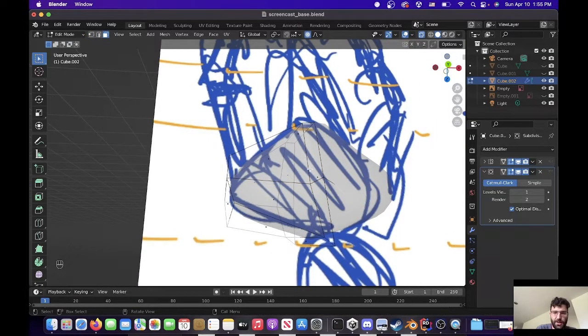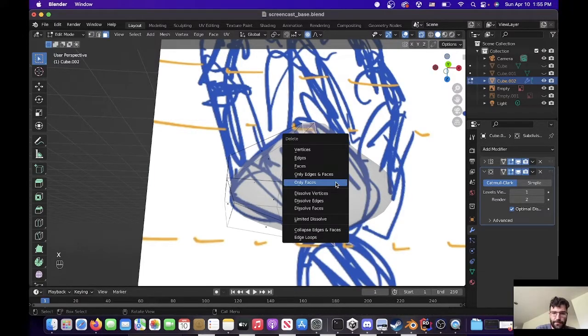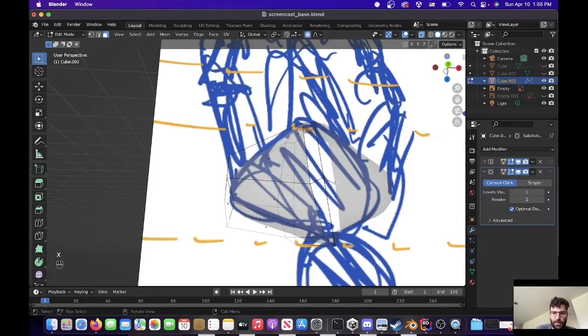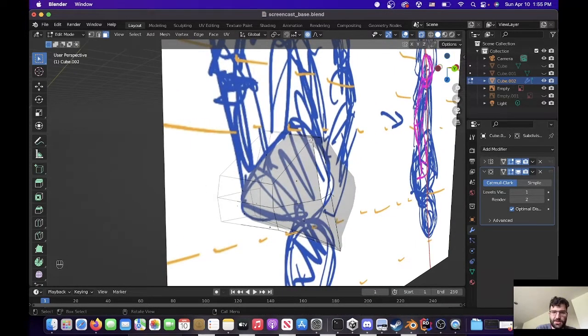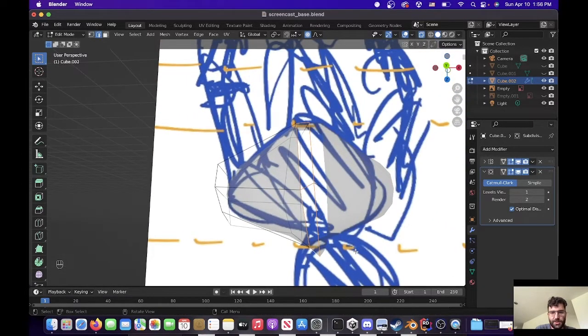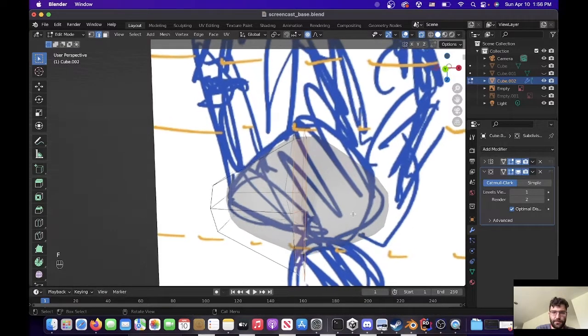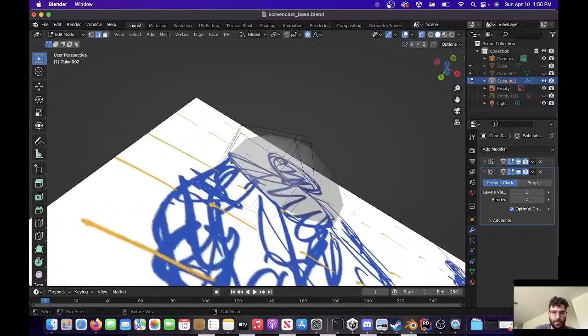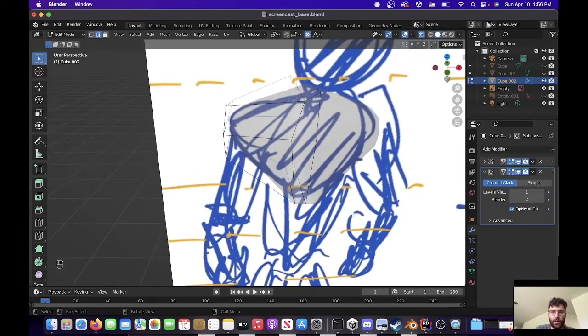It's not the best way because you have a leftover face, and then you have some empty geometry, and it gets messy quickly. So this is not ideal. Like, you want to avoid having to clean up manually like that. But once you've done that, again, you select your loops, make a closed loop. As long as the loops are closed, if you hit F, it fills in magically.